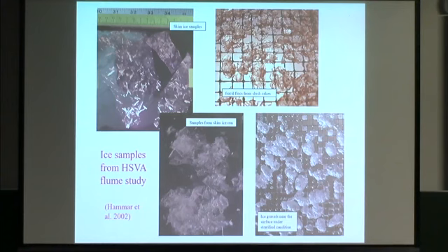And ice can form in different forms. As we see in a very slow flow area, almost quiescent, this is the kind of ice you will see. Okay, we call it skim ice in river people. Not quite the same as grease ice, but anyway, it's very thin sheet of ice floating on the water surface.